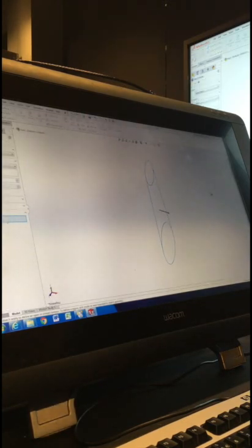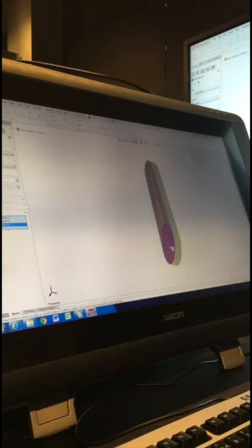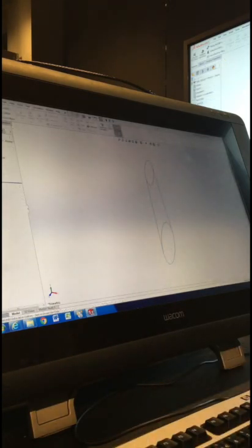Now, the way I'm showing you here is just to explain a little bit about contours. What we've created with the shape around the outside, with the two circles and then lines on the sides, is a shape with 3 contours. So we have a top section, a middle, and a bottom. Typically, we want to avoid doing this with our sketches and our features because it can lead to errors down the track. What we want to try and do is just have one open contour that we use for the extrude. So instead of extruding this way, which you can do if you really wanted to or needed to for a particular reason, if you had a really complex sketch and you just want to pick out a few sections of it, instead, what we want to do is go back and edit the sketch.